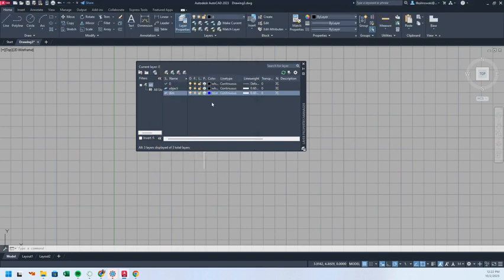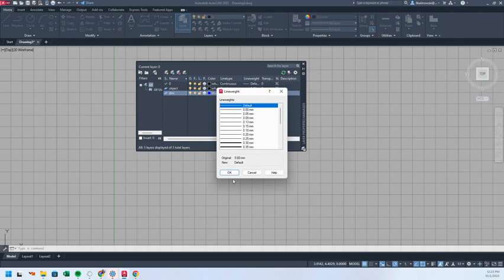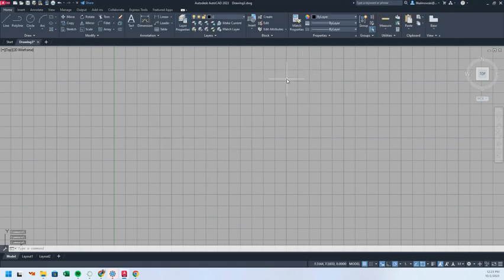I can see a darker blue, but you might choose a lighter blue. Keep it continuous and then go back to default thickness. If you go to our top pull down, you'll see where our layers are. We're going to go to our object layer to start.